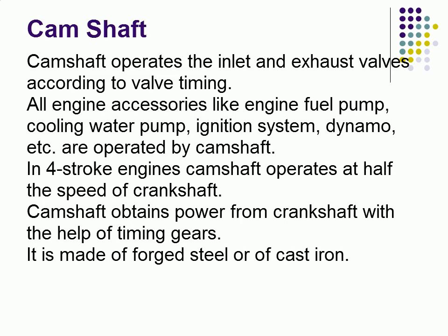Next component is the camshaft. Camshaft operates the inlet and exhaust valves according to valve timing. All engine accessories like engine fuel pump, cooling water pump, ignition system, dynamo, etc. are operated by camshaft. In 4-stroke engines, camshaft operates at half the speed of crankshaft. Camshaft obtains power from crankshaft with the help of timing gears. The camshaft is made of forged steel or of cast iron.